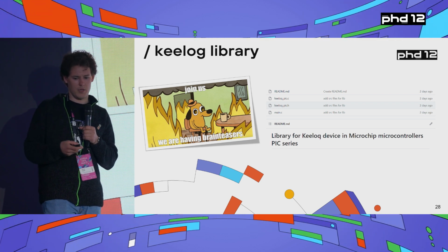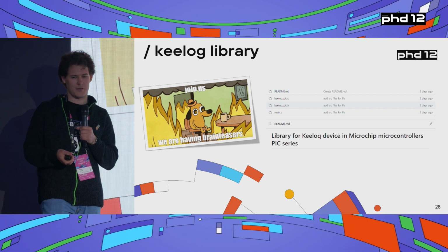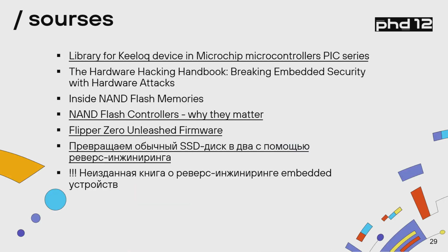I had to test it, I had to play with the order of writing bytes to these 4 registers. I had to play with different sequences of writing bytes to these different registers, but finally I cracked it. So this is part of what I do when I do reverse engineering of hardware and microprocessors.